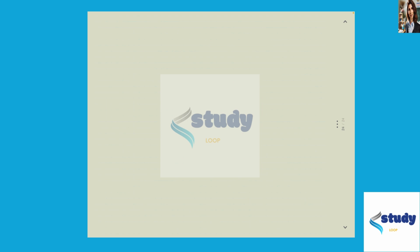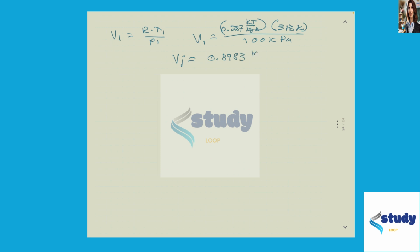Okay, and now we can use the ideal gas law. We can calculate our specific volume. So let's rearrange. V1 will be equal to R T1 over P1. So V1 will equal 0.287 times 313 over 100 kilopascals. And this will equal 0.8983 meters cubed per kilogram.